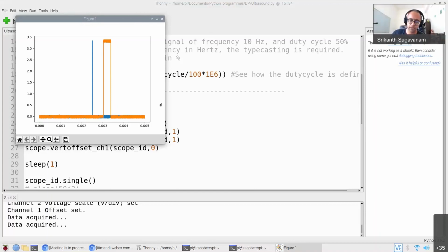You can also use the Arduino to connect with digital sensors, but my recommendation is if you're using sensors like accelerometers, temperature, humidity, pressure, or even sound, work with the Arduino Nano BLE33 because it has got a smaller footprint. It's smaller in size and already has everything in it. There are already libraries out there so that you can quickly start. You don't have to physically do any soldering or breadboarding or anything of that sort. So explore the Arduino Nano BLE33 option, and that's very good.